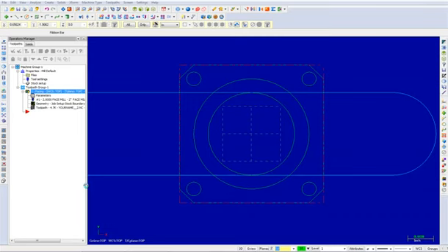In this video, I will show you how to circle mill the inside hole. Circle Mill Toolpath removes circular pockets based on a single point. You can select either point entities, center points of the arcs. Mastercam will then pocket out a circular area of the diameter and to the depth that you specify.